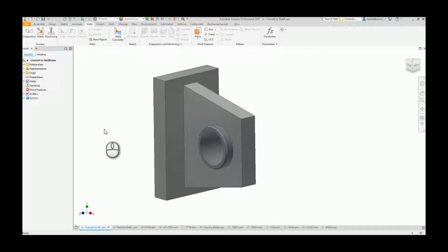Just keep in mind you're exporting that Excel sheet, and once you export it, it's disconnected from the model. So if you change any of the models, you'll have to go in and run a new bead report. And one other point to note is when you do hit that bead report, you can include all the sub-assemblies that come into this. So if you have sub-weldments that come into this, you can have those added to the same Excel sheet.